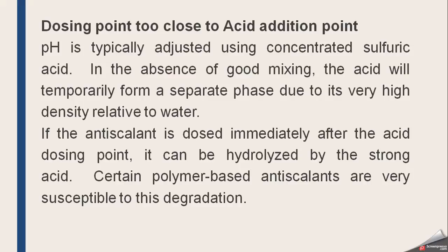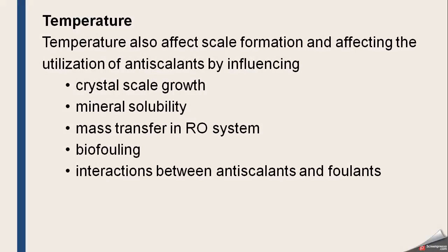So we have to create both dosing points at a certain distance so there will be no effect, or you can say that before we add the antiscalant, the acid is completely dissolved and performs its function before it comes to the antiscalant.